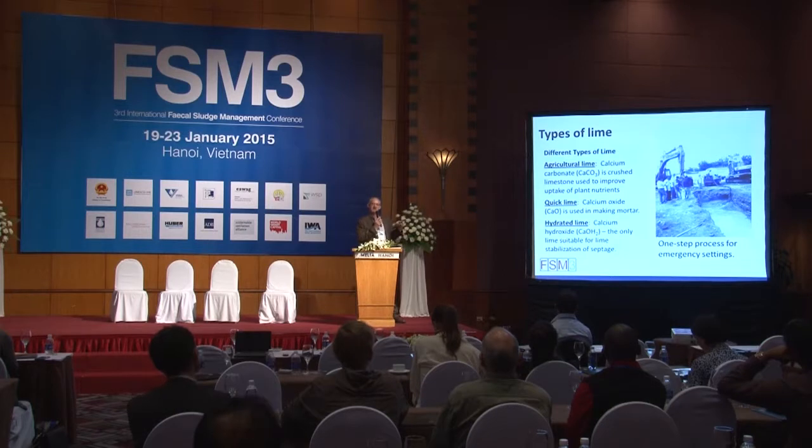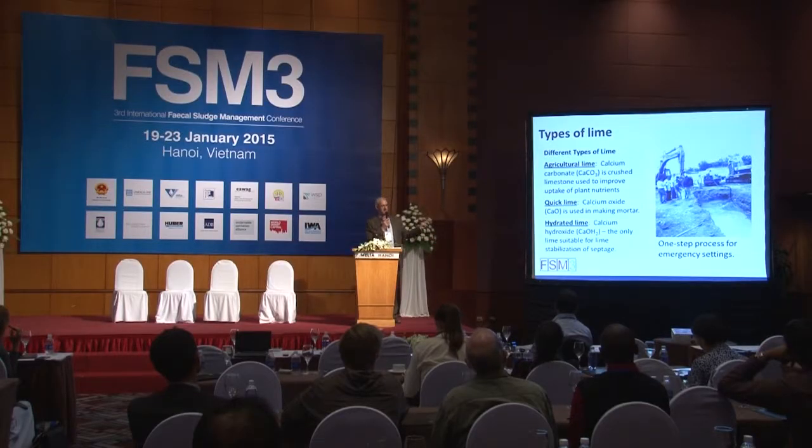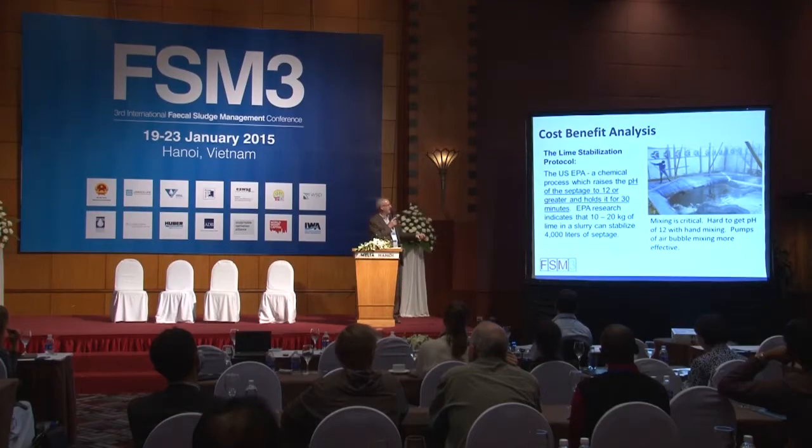Now, in an emergency situation, if you can get 20 guys and gals together with shovels, you can dig a trench pretty quickly. Here, these guys had access to heavy equipment, which made that easier. But it's basically dumping the fecal sludge into the trench, mixing the lime in, and then after a few days, covering that trench and digging another trench. This is a very, very simple, low-cost, easy, fast method of treating and disinfecting your wastewater.